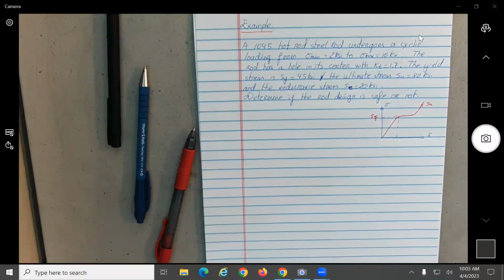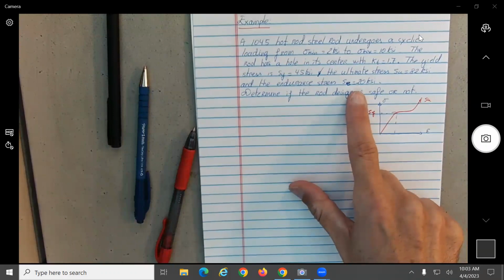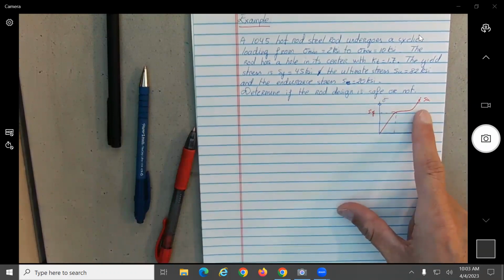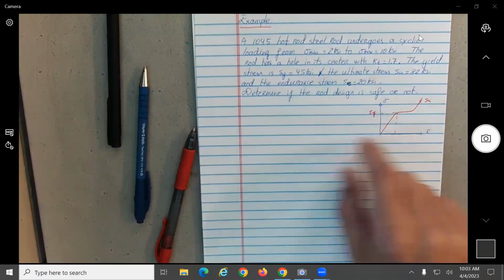Where is the endurance coming from? The endurance is coming from attaching the specimen to, let's say, a shaker, and you move it this way until it fails. That is from fatigue. When you have an object subjected to fatigue, the stress at which it is going to fail is much lower than the yield or the ultimate. That's important to notice, okay?